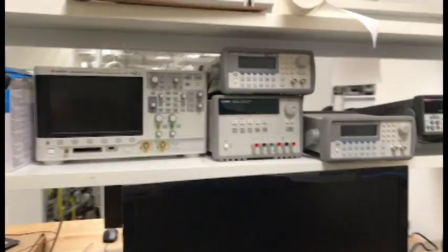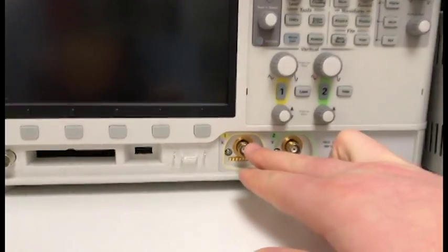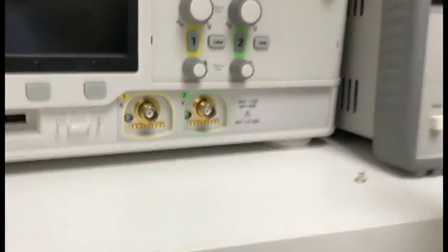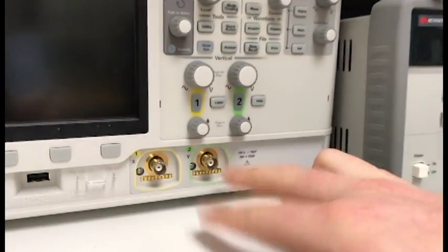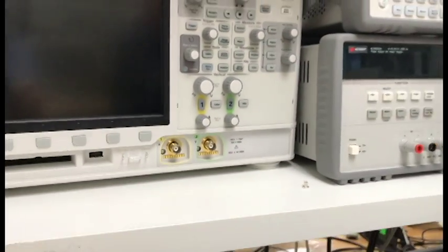It's pretty cool. Basically, you take a probe here, and it's not turned on right now, but you can have up to 2 probes on this particular oscilloscope. I've seen ones with up to 4, and essentially, you can have 2 probes on 2 different parts of a circuit, and you can measure the differences in voltage drop, or you can measure how quickly current is flowing through a circuit like that, and that allows you to take it a lot further and do a whole lot of measurements with efficiency and power output and all kinds of crazy stuff.